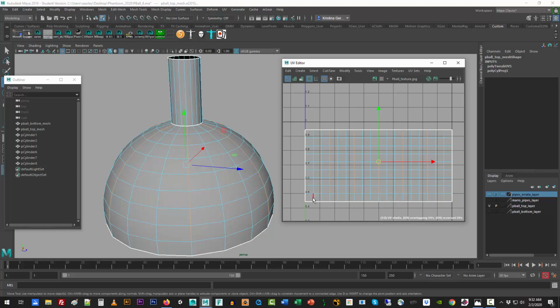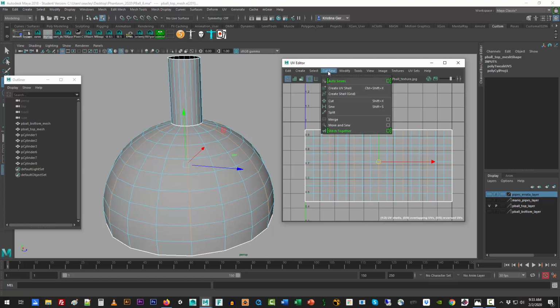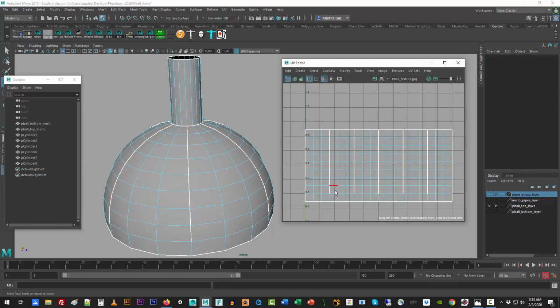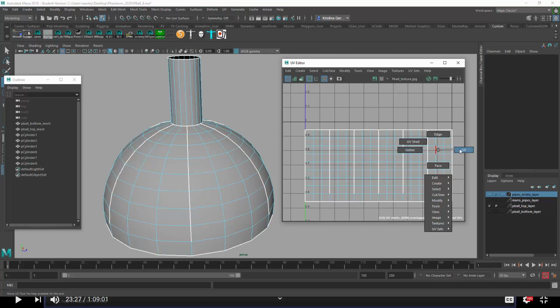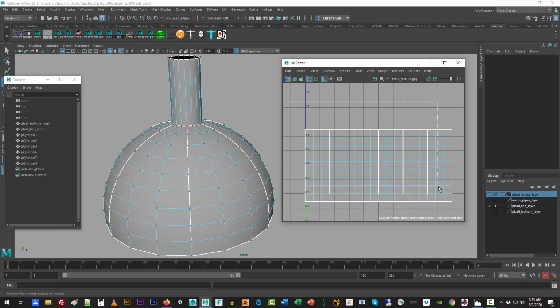So now we have an uninterrupted line of polygons that is anchoring the operation of cutting as well as relaxing these strips. So we can come in and cut it, and I'm going to click off the object to validate that, with the border on, these are the exact strips I want. I'm going to go in then to UV selection mode and select just what I want to relax, and I'm going to avoid touching anything on this line, on these edges here, as well as the edges above it.